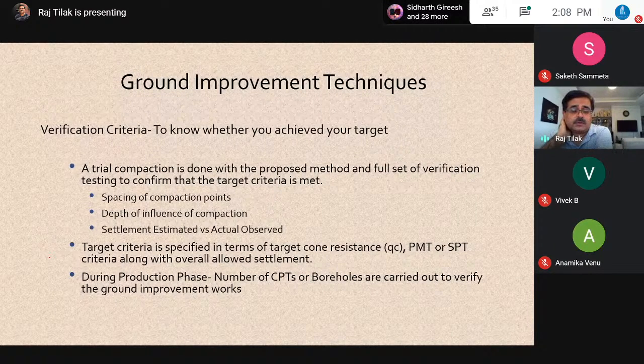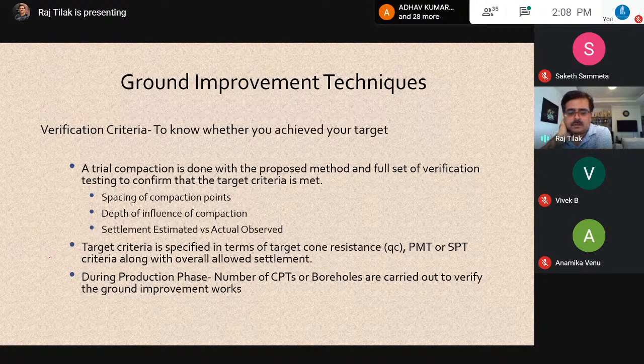One thing we can cover later on is how CPTs work for carbonate sands. Here in the Gulf, you see a lot of reclamation going on, whether it's the Palm or anything. It's all done in the sea, so it's a very common practice here. They have faced challenges here, and a lot of literature has now been written on what happens if the carbonate content of the sand is much higher. CPTs do not perform the way they perform on normal silica sand.